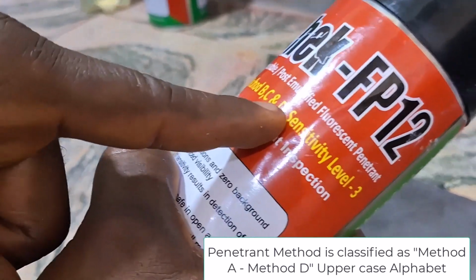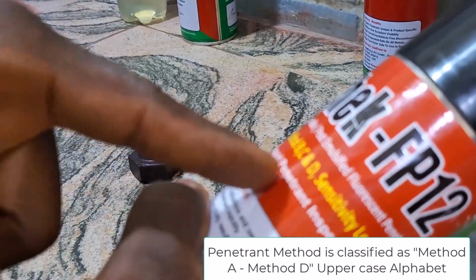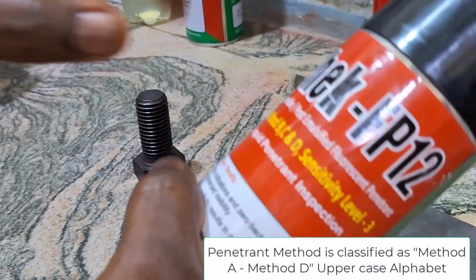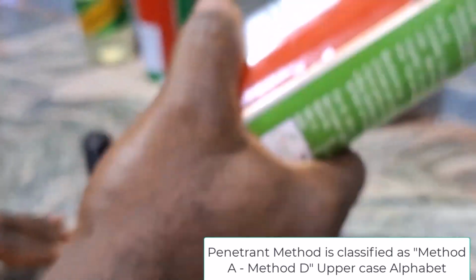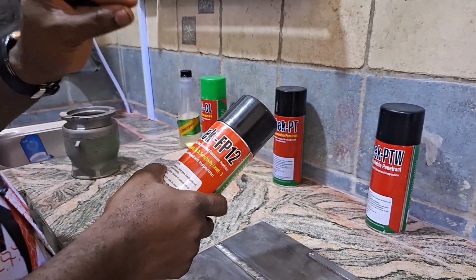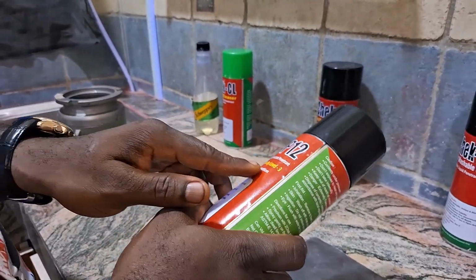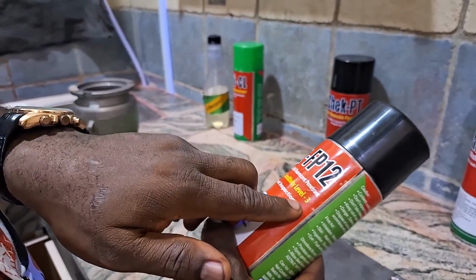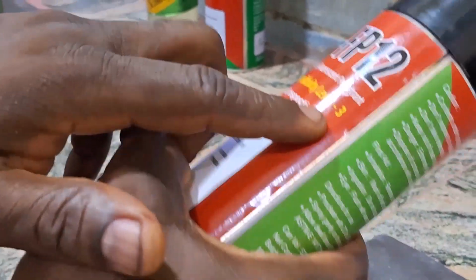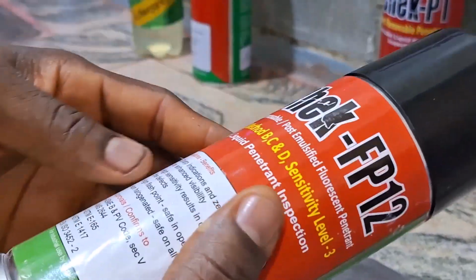Method D is post-emulsified hydrophilic, while method C is your usual solvent removable. So this single penetrant can apply for all three techniques. So you can use it for 1B, 1C, 1D technique. Also its sensitivity here is level 3, which is high. Level 4 is very high, but this is level 3.